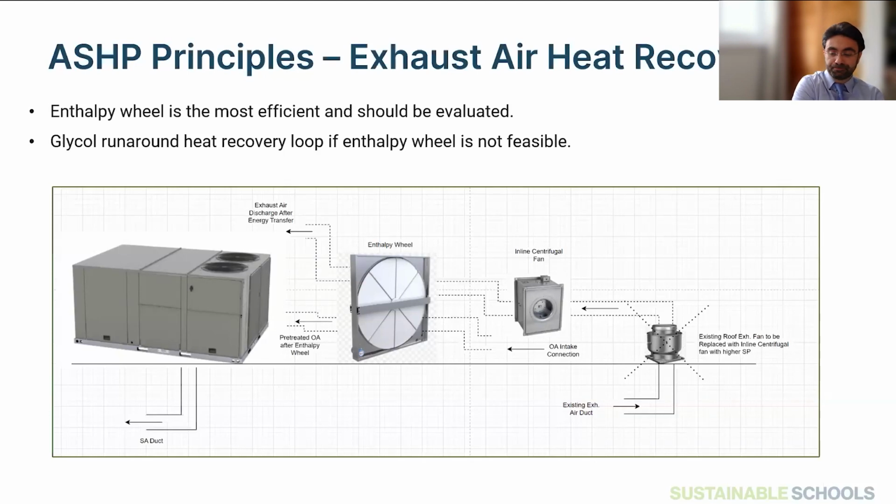with the vapor injection compression that is being used with the latest technologies. However, what comes out from factory as a set point for switchover between the secondary to the auxiliary heat stream, like the gas, typically it's between -5 and 2 degrees C. This is what comes out of factory. We've also heard that for some cases it's project dependent, depending on the heat load of the building and the application, and can go down to -15.